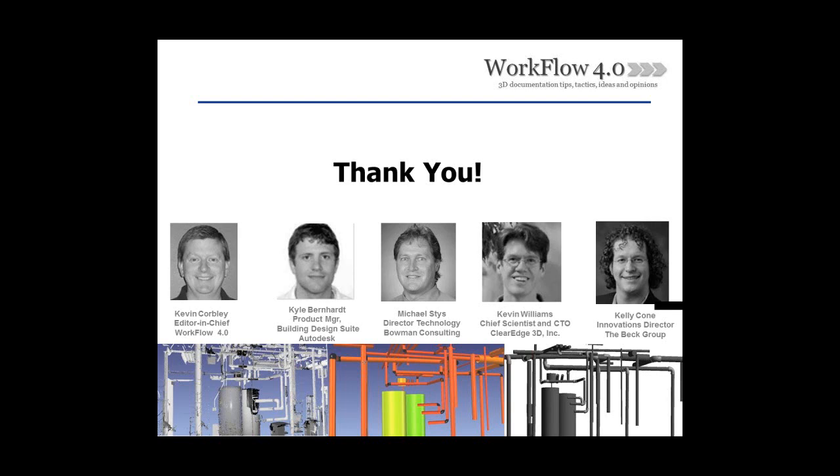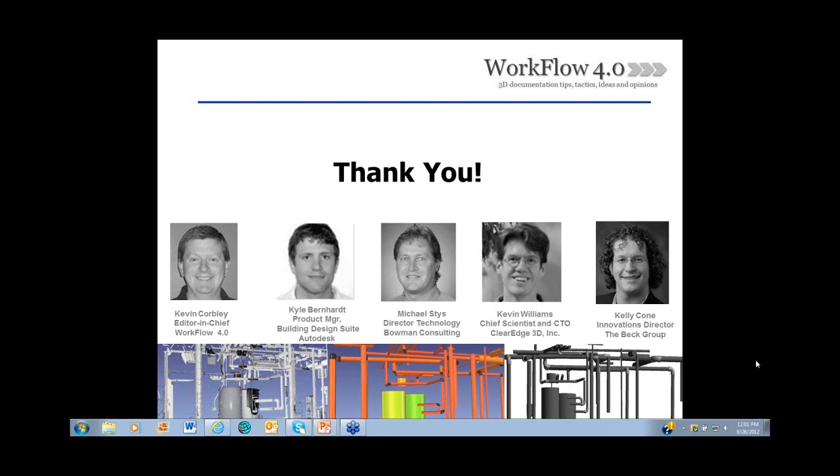Great. Kevin, can I follow up on that? Sure. From our experience with the tool, and also being one of the beta testers for version 3, it has a whole lot to do with the density of the scan. A lot of our scans for architectural space are still done using time-of-flight scanners, and we generally find we get much better results out of phase-based scanners just because of the point density. So, if you're anticipating using these tools, I think it impacts which scanner you would ask your scanning provider for or select to use. Kevin can probably explain. Yes, absolutely.